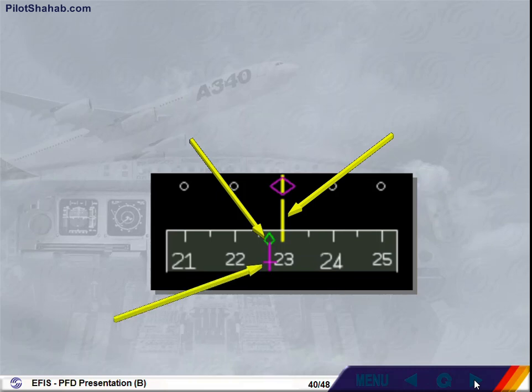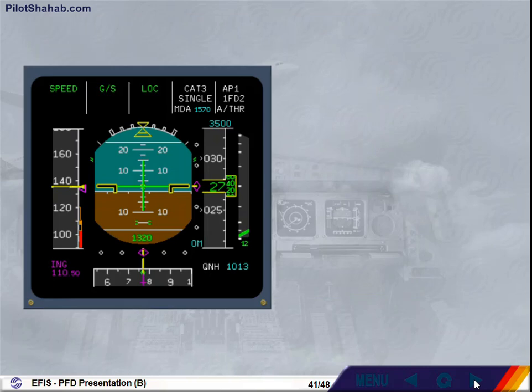The ILS front course dagger is beneath the track diamond. You will see how useful the track diamond can be to help you fly an accurate approach in the simulator phase. You will be given more information on the ILS system, the flight director, the radio altimeter, and the flight mode annunciator indications later in the course.